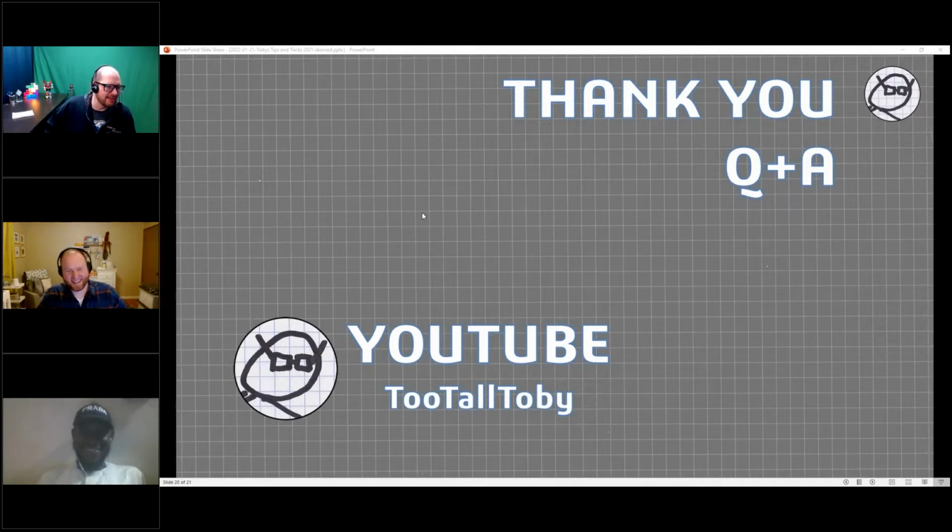Also good for any kind of swoopy lofty guide curve. That's where I've used it a lot. I do a lot more surfacing and swoopy lofty shapes, and it's difficult to get that shape captured using 3D sketch. But if you can do it using 2D, a lot of times you can get exactly what you want. So that's where I've ended up using it a lot.